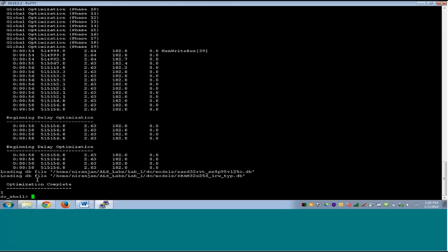There will be many tools that will work on this netlist. For STA you will work on this netlist. For formal verification you will work on this netlist. So we'll also have to think about that. How do we make that process smooth? So many times we choose to not encrypt the design. Many times we choose to switch off the boundary optimization just because we want to make our job easier later in the flow, right? So again we see that this is done.